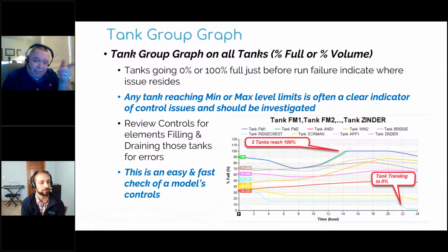But if you get somebody else's model that you didn't make and you're looking at it for the first time, just run an EPS and look at this graph. It will often give you a sense of, okay, are the controls likely okay, or is there something strange I need to investigate? Those min and max levels, that 0% or 100%, are really good indicators of that. But that's a quick check.